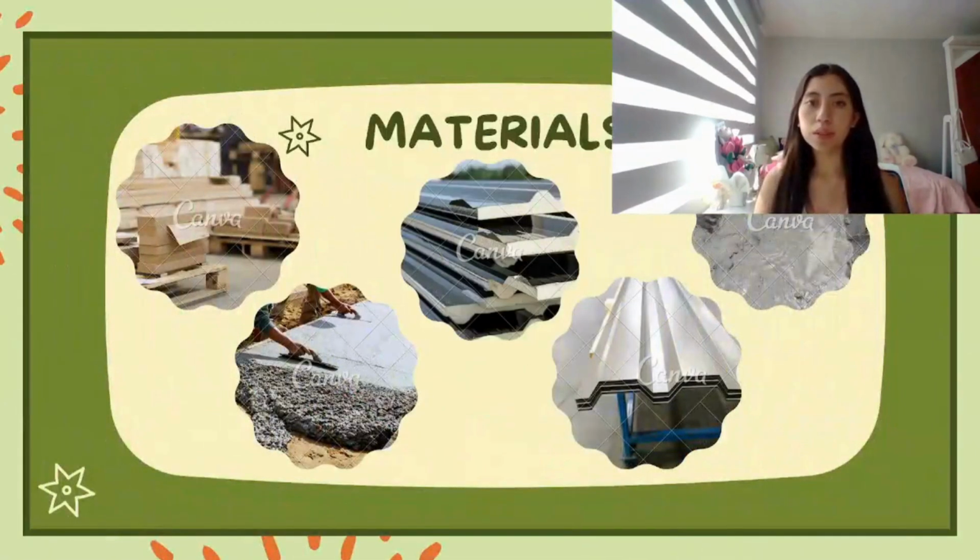The materials used for the construction of an industrial warehouse are wood, concrete, metal, sheet for roofs or walls, and cement. For the construction of an industrial warehouse, first the foundation is made. Then the type of material to be used is defined, and the roof and walls are aspects that are always analyzed, taking into account the use that will be given to them. Finally, the requirements for the best equipment of the shed are evaluated. One of the most important complements is the electrical installations.